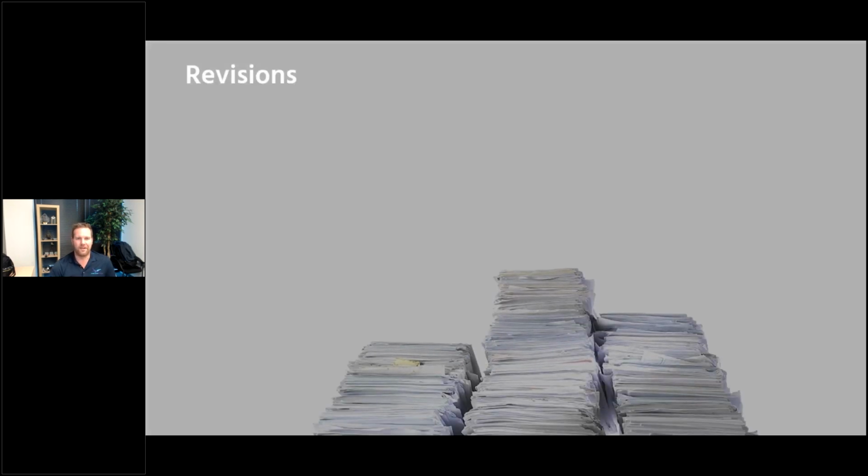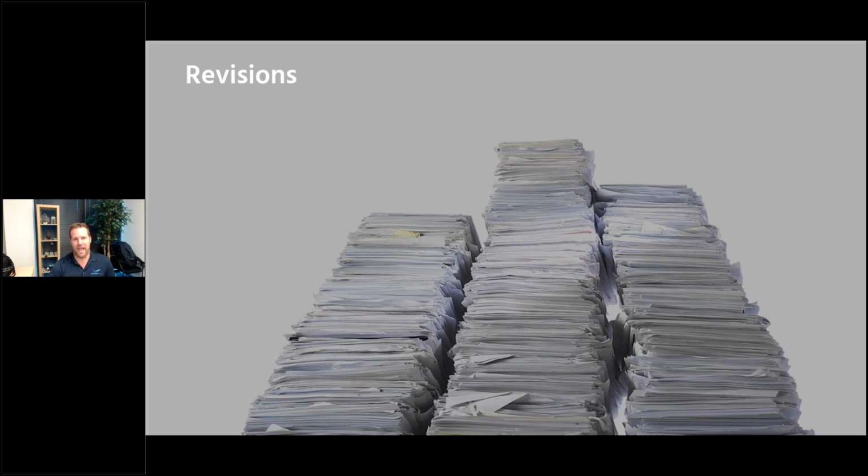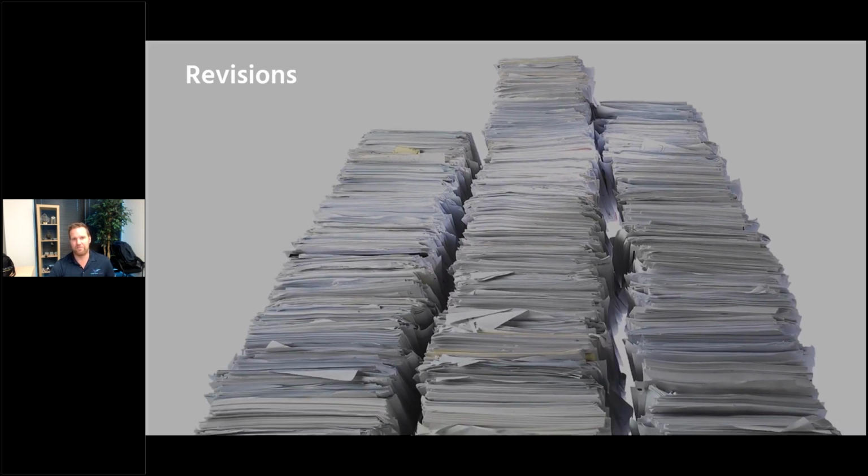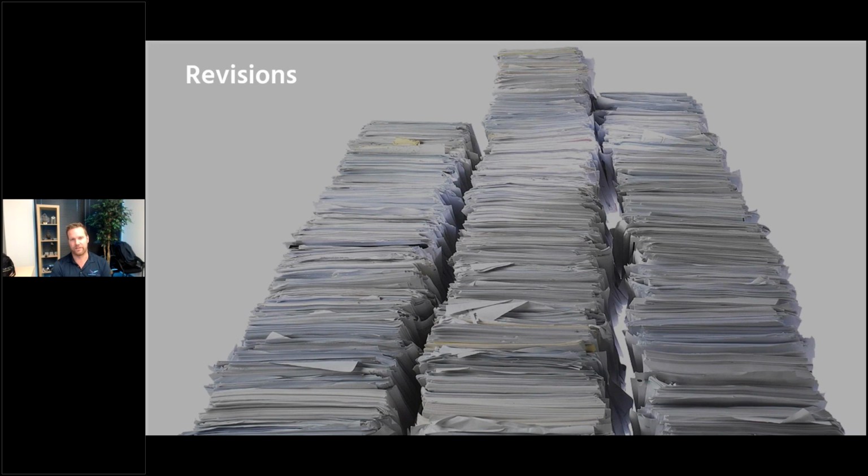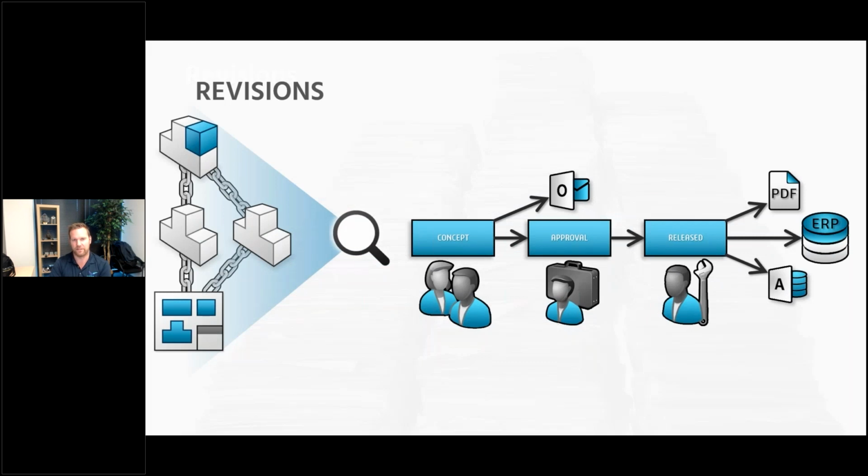And the last one is revisions. You're always going to have revisions. They happen, right? You're going to iterate, whether it's an issue that you need to implement an engineering change for, or whether it's a design improvement. But they're always going to happen. And how we handle that is by simply adding another transition in this workflow, which accounts for an engineering change process. So any of those files that are in that release state, remember they were all read-only, nobody can make any changes to them.